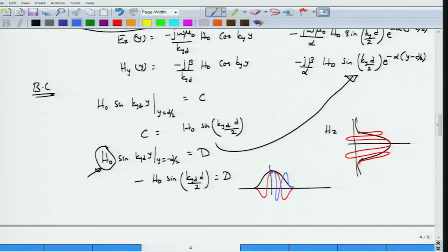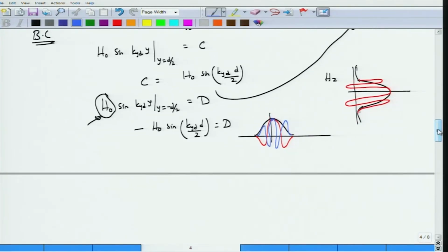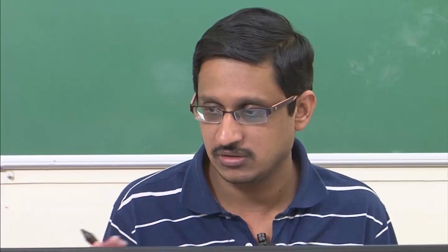This is the next higher order mode. Again, as I said, the drawing is slightly confusing for me, but these different modes correspond to the different orders. There is no specific greatness about these mode orders. They just indicate the possible solutions as the different mode shapes contained by the electric and magnetic field components. They just come in different flavors in which sustainable E and H patterns for the particular solution would exist. So these are called modes.